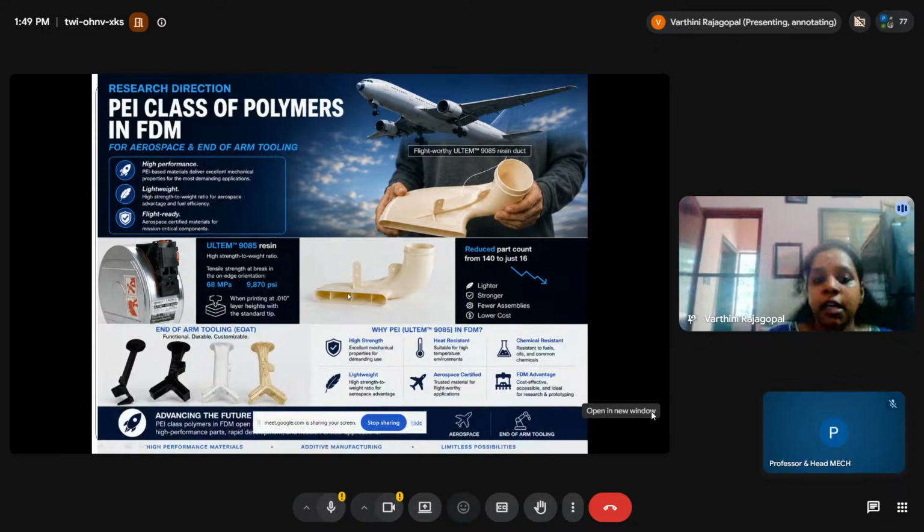Okay. We then finalized on the hexagon structure, and after finalizing that, we did topology optimization. We didn't want to build an implant in this profile. We wanted to further reduce the weight of that particular implant and make it stronger, right? So we did topology optimization. We applied the loads that are going to act on the vertebra. Like we applied the compression, we applied the flexion, we had axial rotation. So those kinds of loads we applied, and we finally generated this topology optimized profile.